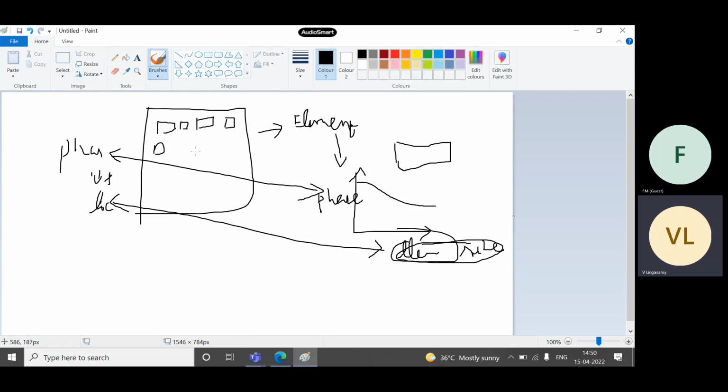For example, with the help of MATLAB code, I find that here I have to compensate 240 degrees. I will go and check which element size is giving me 240 degrees. For example, this element, say x1. The x1 size of my element is giving 240 degrees, so I will place an element that has x1 dimension.